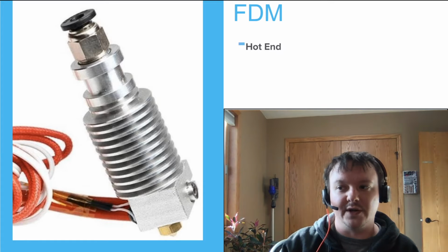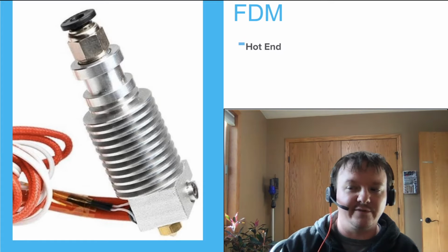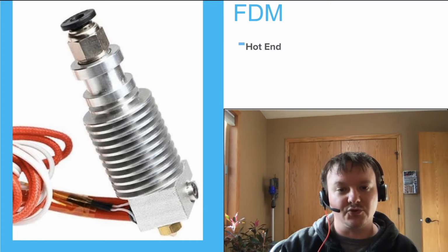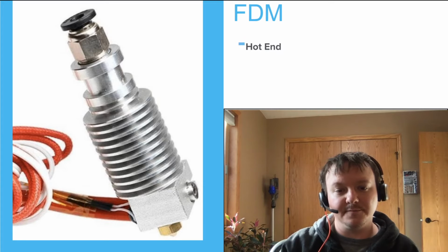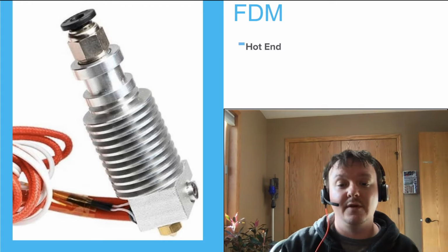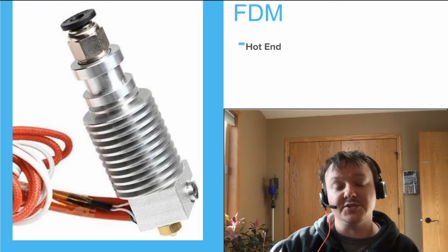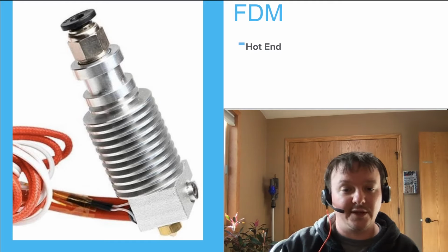Large nozzles are great if you want to stick out a lot of filament, make something that's very strong. It's great for very high print speeds if you want to print large items. And then there's smaller nozzles as well if you want to have much smaller features. If you're trying to get down into the inch tall miniature range, a smaller nozzle will certainly help with that.